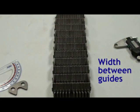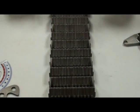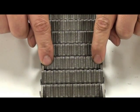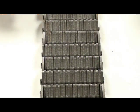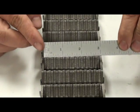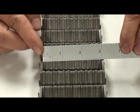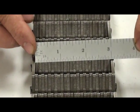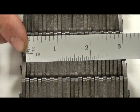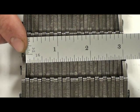The width between the guides is the distance between guide links and applies only to side guide or multi-guide chains. With the chain laying on a flat surface, locate the guide links and measure the distance between the inside edges of the links. In this sample, the width between guides is 2 15/16 inches. The width between the guides is important because this defines the space that the sprocket tooth must fit into.